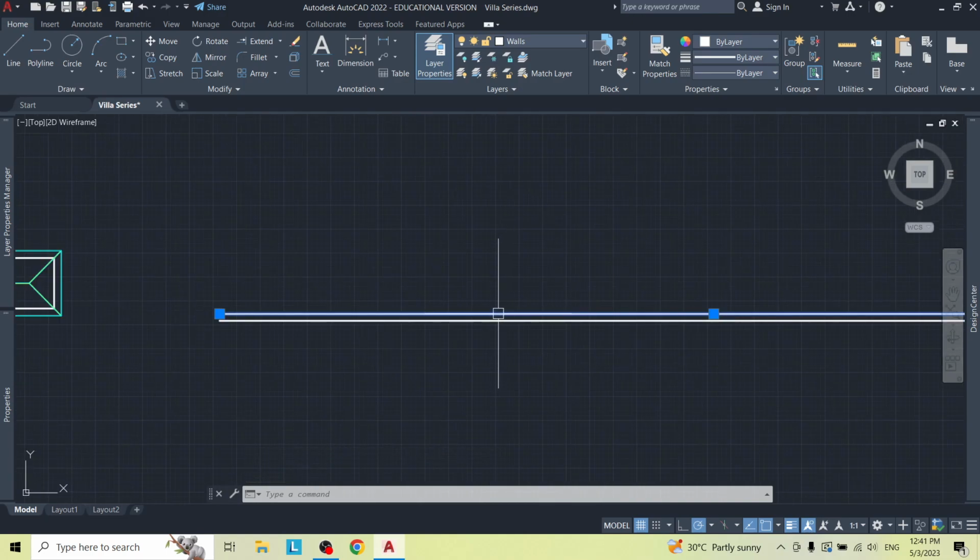So from this floor to the top of our walls, we can have 10 feet. CSEC might give you the measurement. They might tell you from the floor to the top of the ring beam, or from the floor to the top of the wall. Whatever they call it, that's the top of your wall. Ring beam or the top of your wall, that's the measurement. If they give you that measurement, use it. Otherwise, this is what I want you to do.